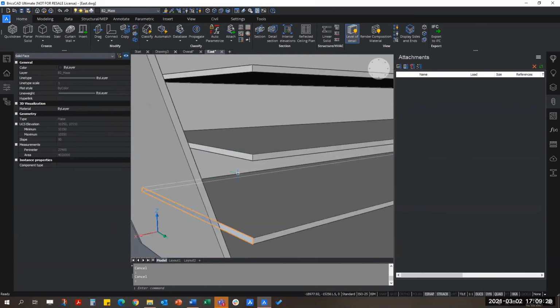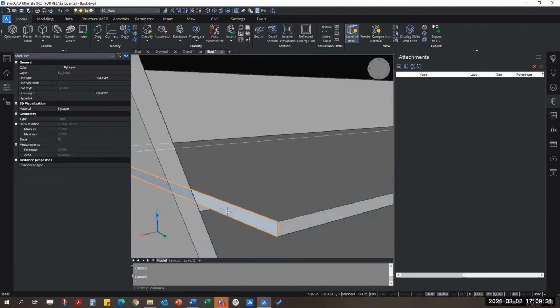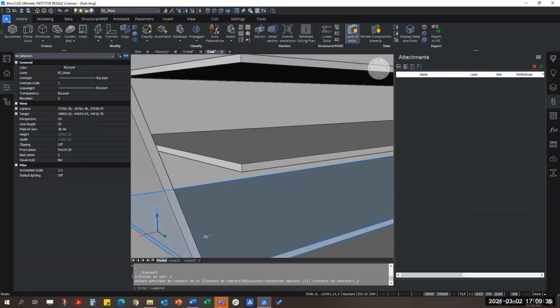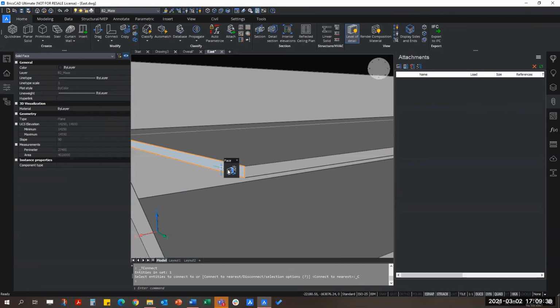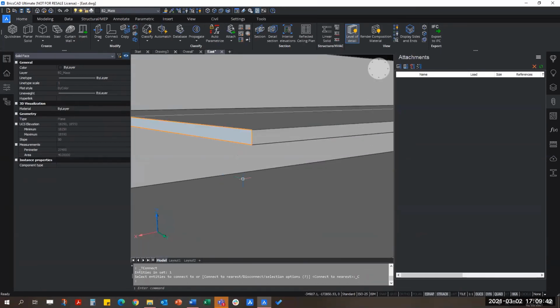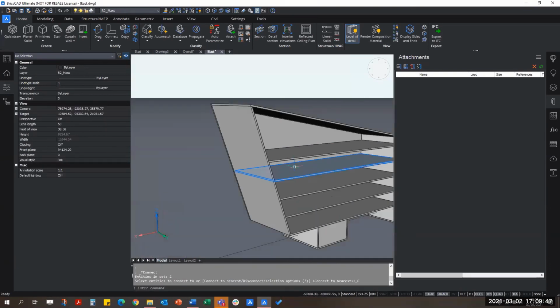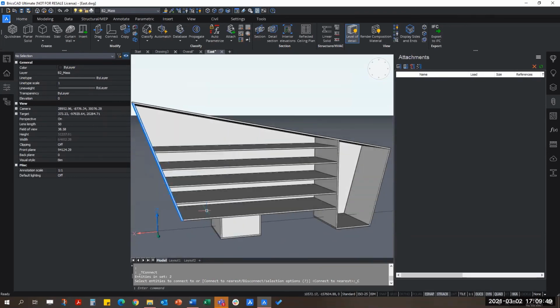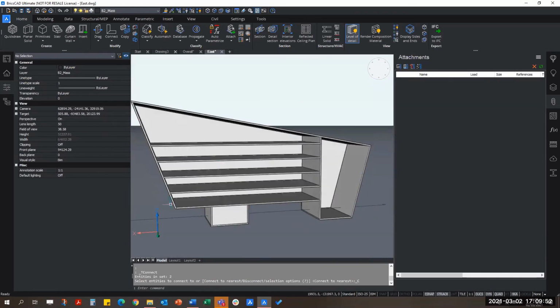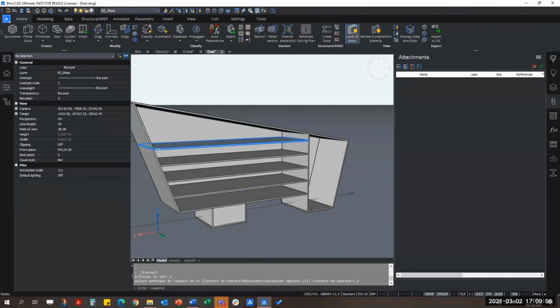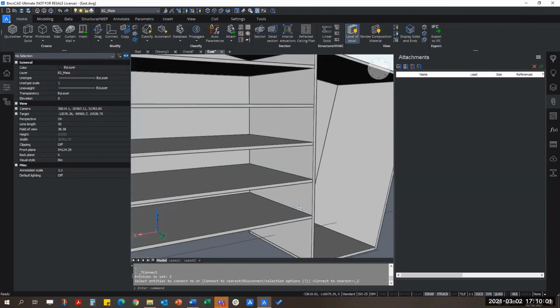And once I'm happy with it, again, I'm going to do this, connect to nearest, and because I've used that one now, the next one on my quad, you can see the AI tool is kicking in again. Now I think you can even double select it. There you go. You can select multiple faces, shoot it this way, and here you go. My floor slabs are touching this side of my external wall and internal wall.